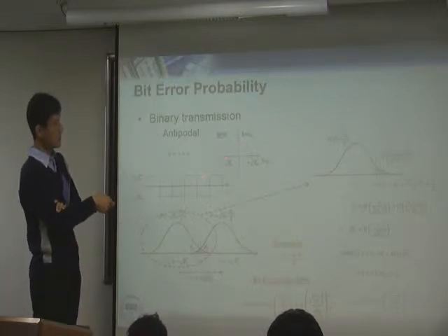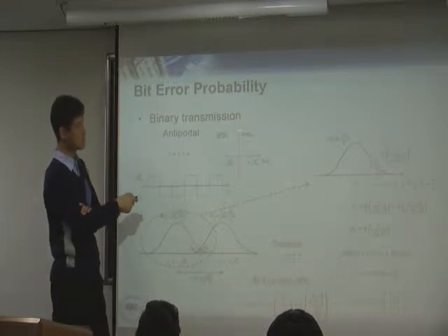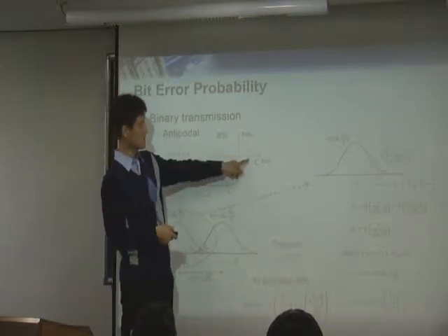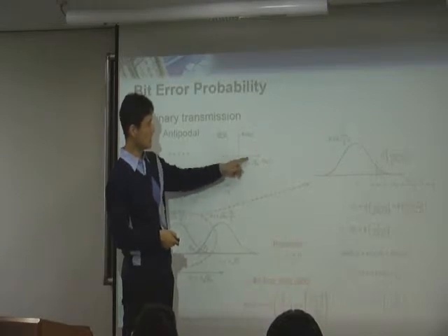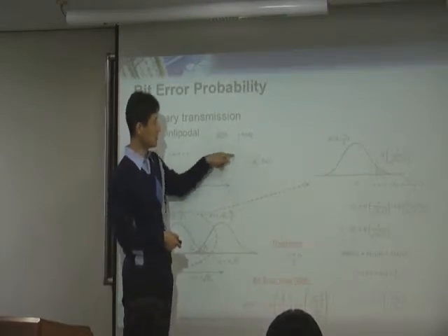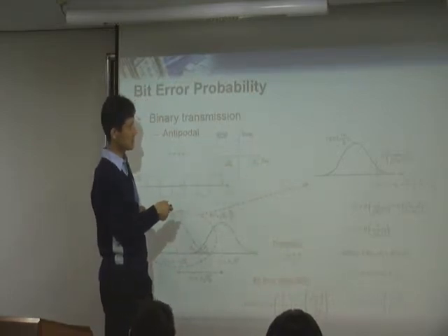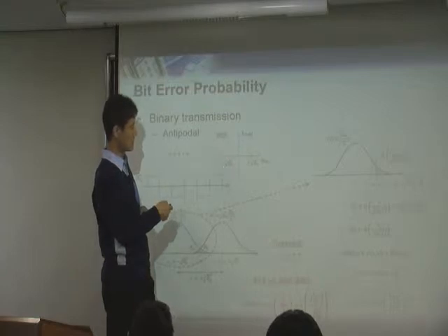If you plot this time domain signal into the constellation domain, you have a positive value and a negative value, okay? Since this is BPSK, both points are on the real axis. So you have some positive energy, negative energy.